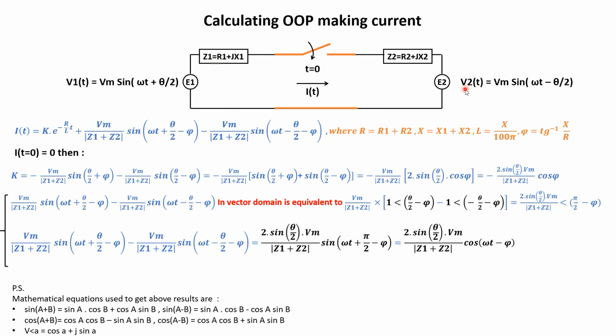So we have a very simple RL circuit that is going to close at t equal to 0, and these are the voltages. Then, for the current, again with superposition, we have a DC component and the final steady state, which again, I emphasize, is not the actual steady state, but a kind of steady state at the short circuit study.